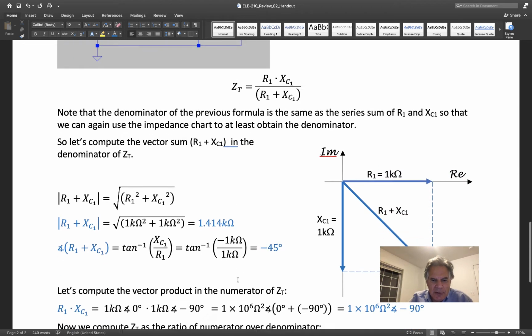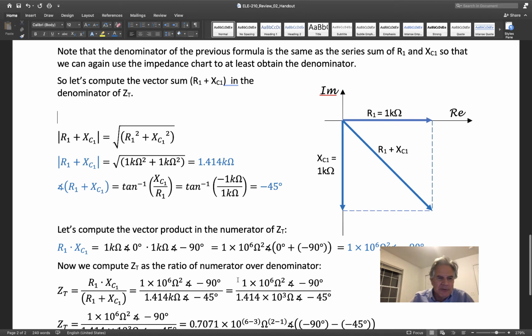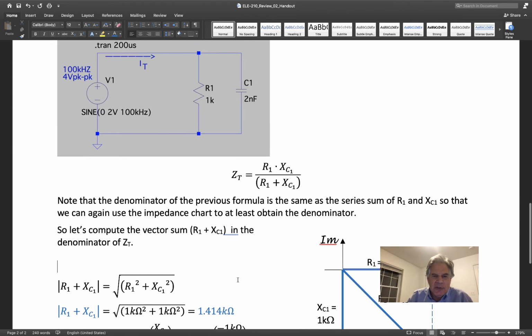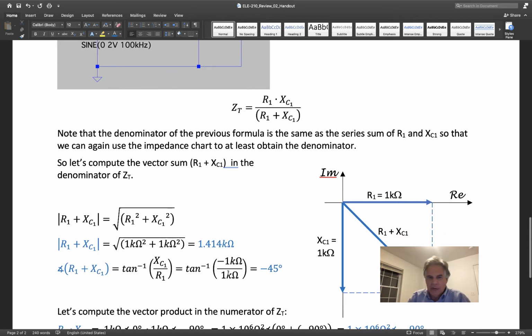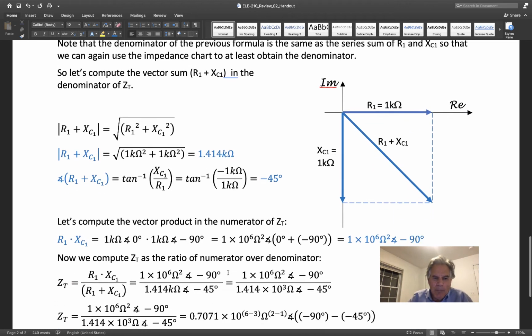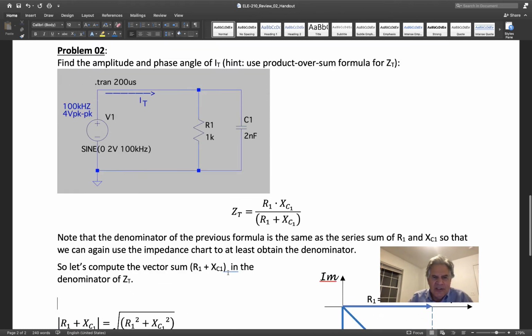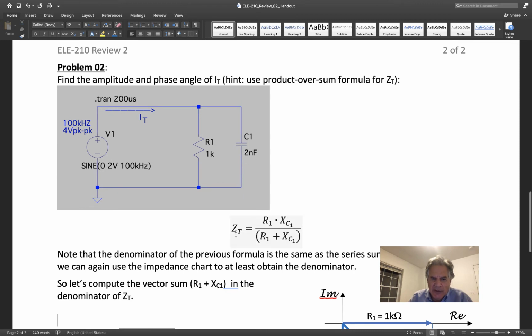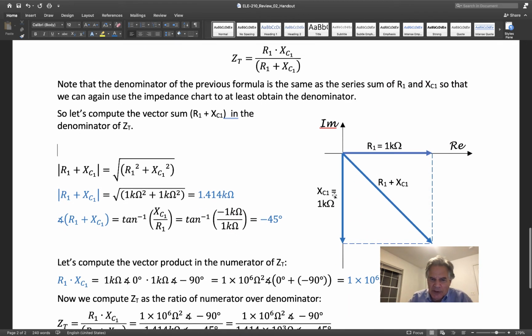I think I've committed a bit of a faux pas here, and I just assumed the capacitive reactance. I got a feeling that this should be about 1.59 nanofarads, okay? So we'll take a look at that, and I'll put a note in the file. But let's just say this capacitor has whatever value gives us 1,000 ohms, because I went ahead and did this.